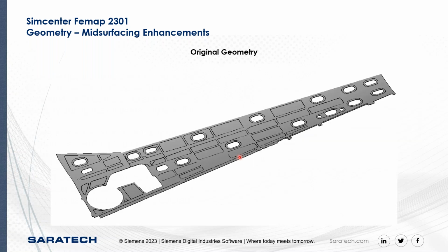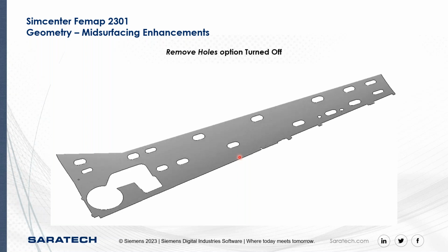So say we have this pretty flat part here. This is the original geometry. We're going to use the automatic mesher on this. We can see there's a series of imprints and some holes. If we had the remove holes option turned off, this is the automatic mid-surface that we would see, and we can see that all of these holes still remain in the part. Obviously, we could go back in and delete all of these, but that becomes a bit cumbersome.